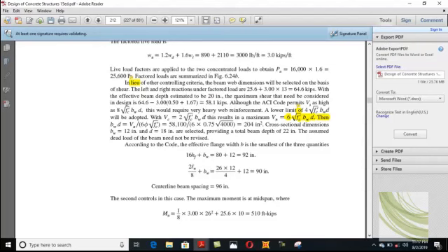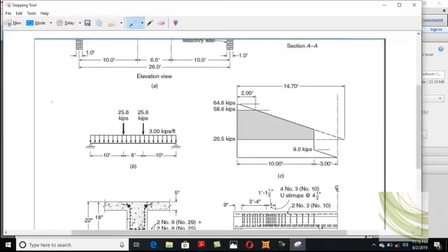I want to clear you this step, that from where this 58.1 kip basically comes out. As we see that they consider the effective depth equals to 20 inches because we have this 54.6 square, this is the mat here, and this 20 inches is the effective width because we have 24 inches overall depth, and keeping 4 inch as a clear concrete cover, so you will get 20 inches,